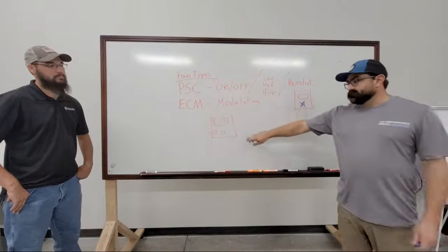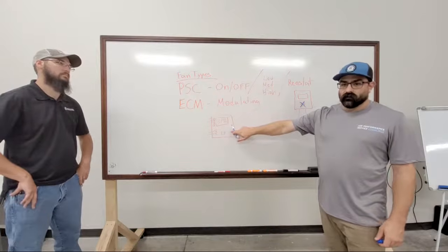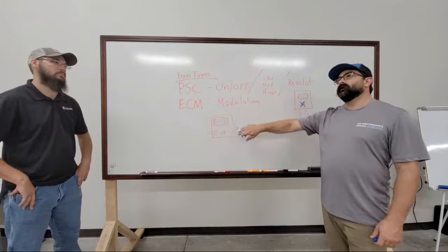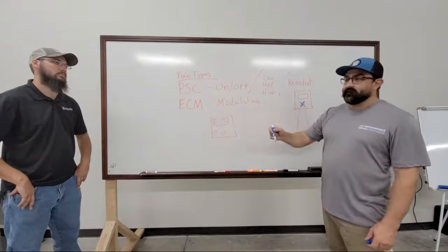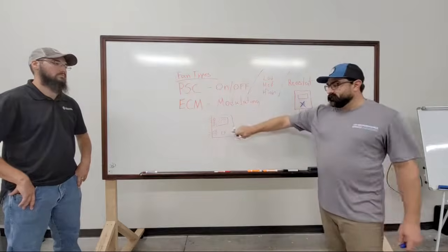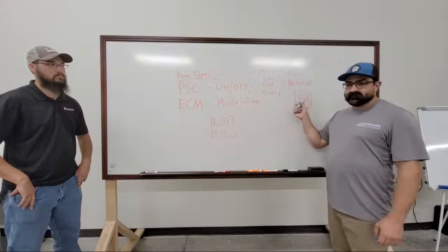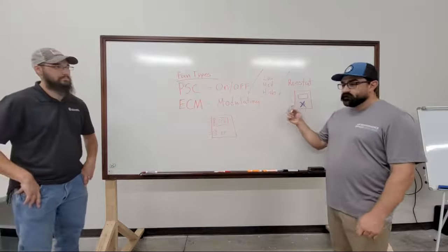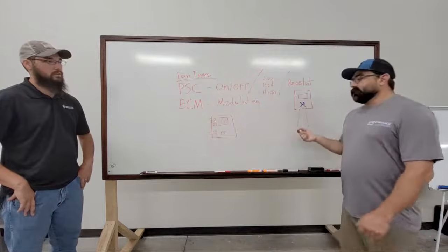These are a little nicer because you get RPM. Because it is set to an RPM, once you put the ECM motor back in, it will go to the same RPM because of the way this board works with the chip inside of it. This is just simply changing resistance. So if the new motor has less resistance than the old motor, this needs to be recalibrated.